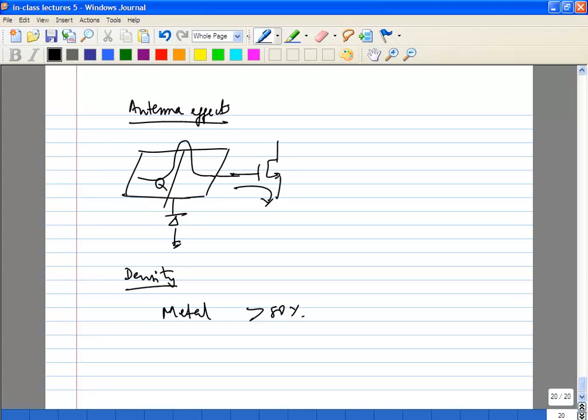So you'll have to put in what is called dummy metal. They'll be just floating pieces of metal. So your block may be here, and on top of that, they'll put in dummy pieces of metal on all metal layers. Okay, it will just be an array, and typically you won't even be able to see your circuit once it's filled. Now obviously, for sensitive circuits, you want to prevent this.